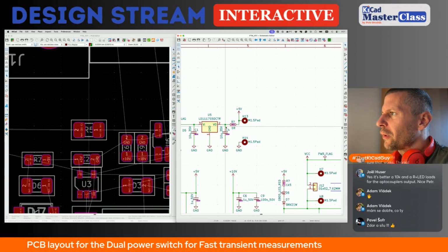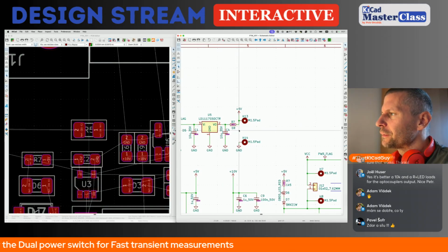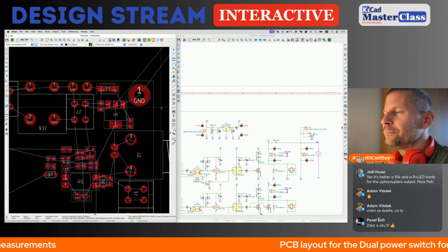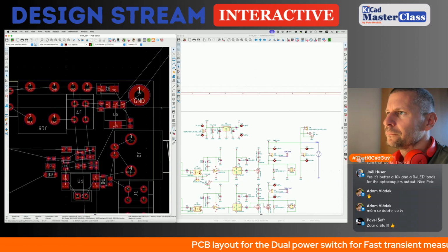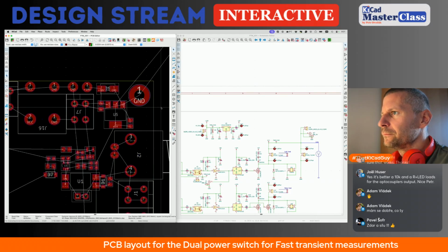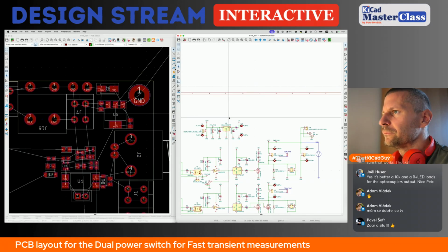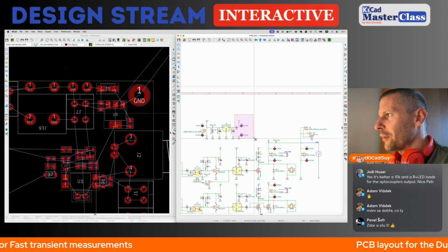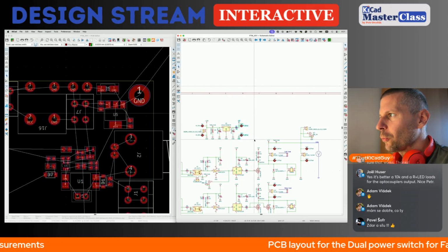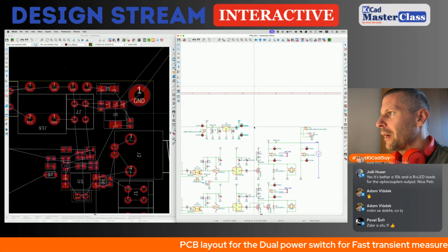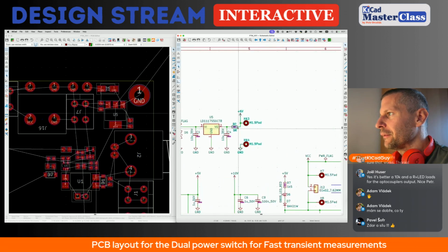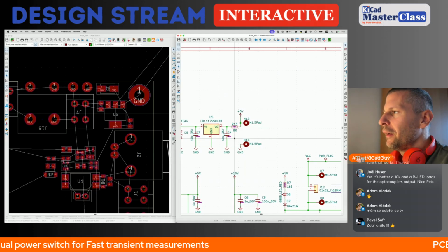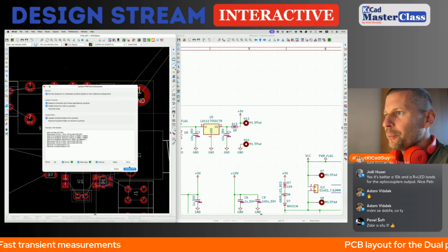I have to isolate the output of the LDO, because the best way would be using a jumper. But the probability of using the external 5 volt or similar voltage is very low. And if that happens, I'm ready to unsolder the 0 ohm resistor. Most of the time the 0 ohm resistor will be soldered.